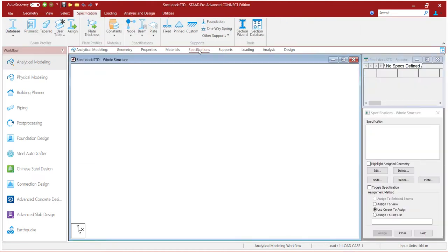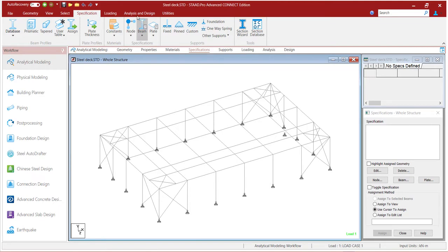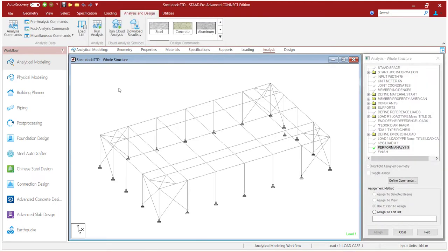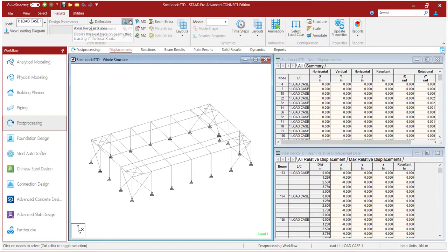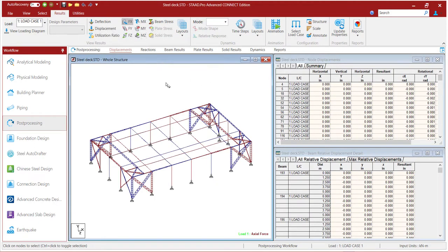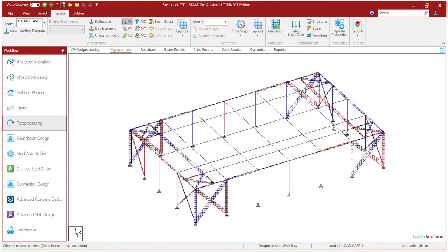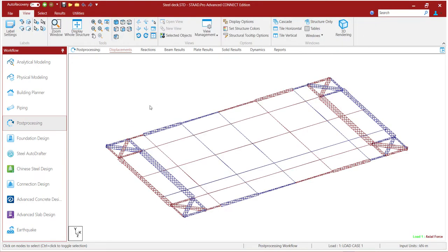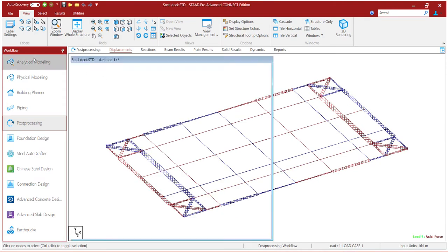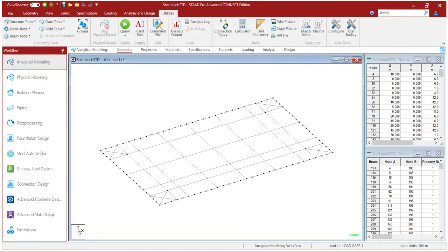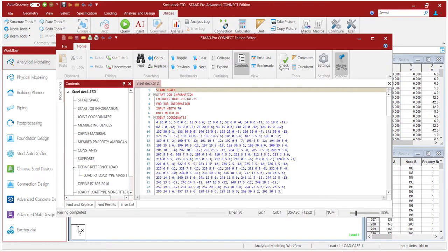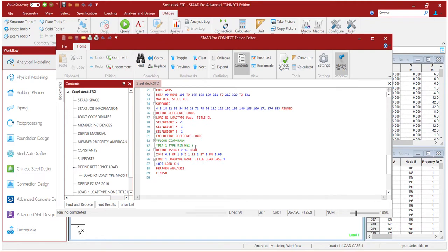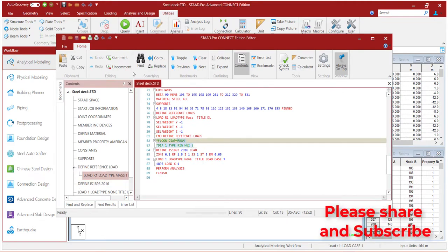After analysis, you can see that in the first situation, where no rigid diaphragm is assigned, there is a significant amount of axial stress experienced by these cross bracings. Now let's add the diaphragm at that very same floor level. I have already created the diaphragm definition. I had just inactivated it in the previous scenario. Now I will just get it activated.